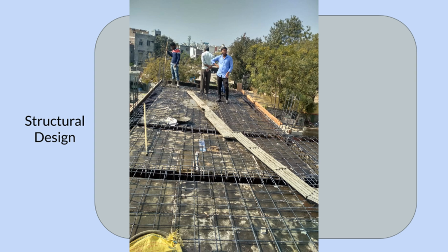If the slab is designed as a cantilevered slab, then the top bars shall be embedded in the beams with development length. This is the case for a chhajja or a projected slab.